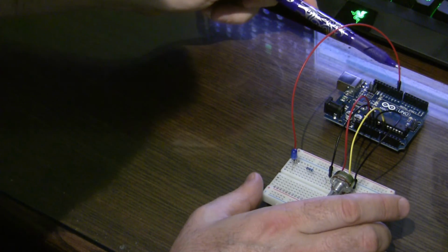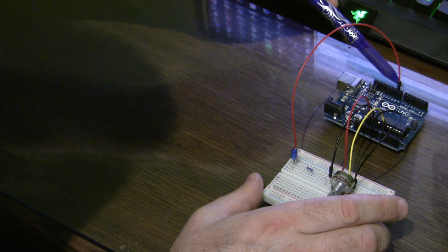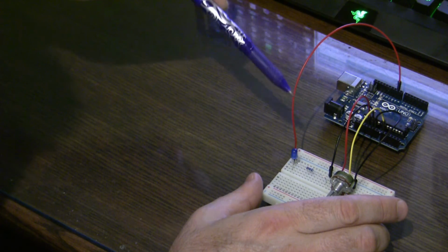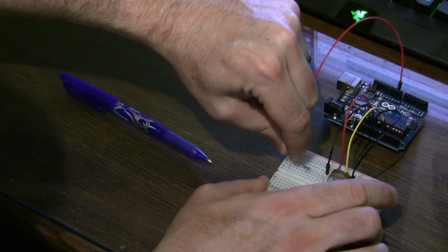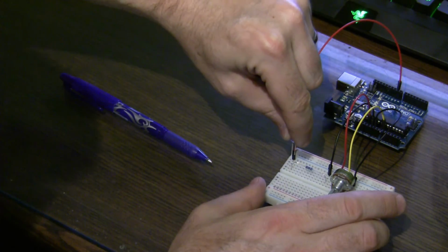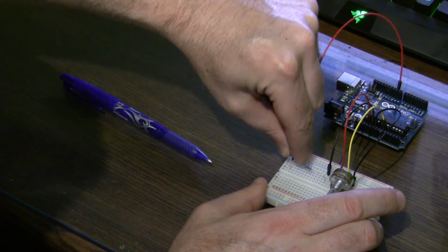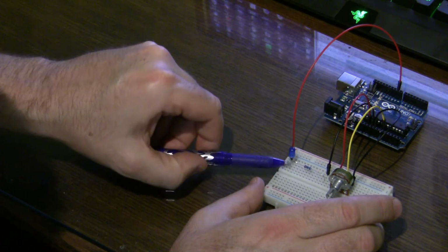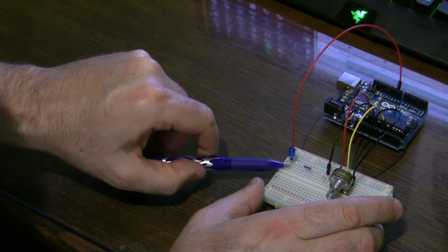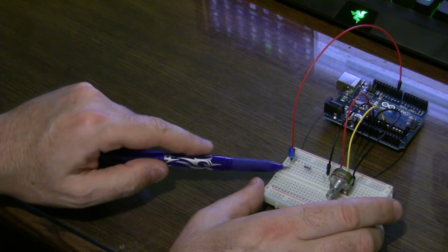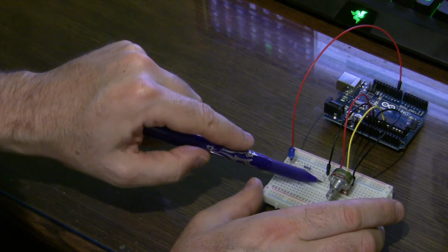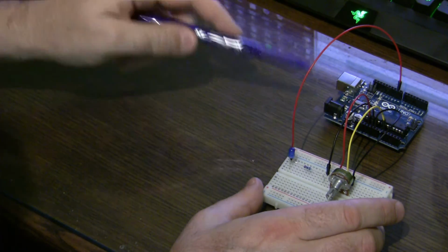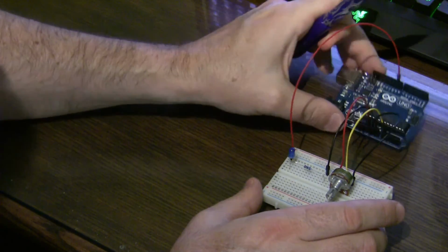So if we take a look over here, here's pin number 9. So that's one of our power sources. That is going to go through the LED. I'll pop that out so you can see. The long leg goes in the same row as the power cable, and then the short leg comes out on the same row as one end of the resistor. So then the flow will go through here, come out the other end, and on the other end of the resistor is one of our black cables that goes to a ground pin on this side.